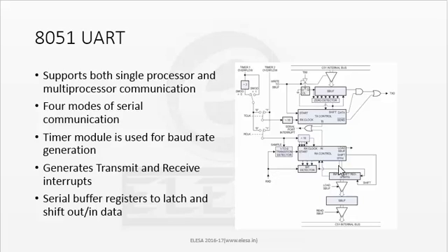So as and when the consecutive bits are received, they are put in this input shift register, and also a signal is given to the RX control block about the number of shifts. Once the number of shifts are over, that is a total of 9 bits are shifted, then the RX control block won't give a shift signal to the input shift register, and the data which has been captured is written to this SBUF, which can be only read and written to the C51 internal bus. So okay, I hope you guys are okay with this functioning of the logic.